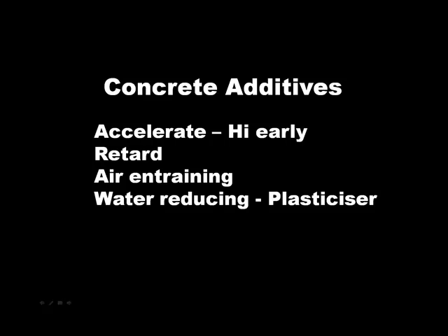You can use additives to the concrete to affect the performance in several different ways. You can accelerate the rate that the concrete sets and hardens, and that is usually called high early concrete. Typically that's used when you're placing some pavement and you want to place that in service as early as possible so that you can shift traffic and move into the next phase of construction.